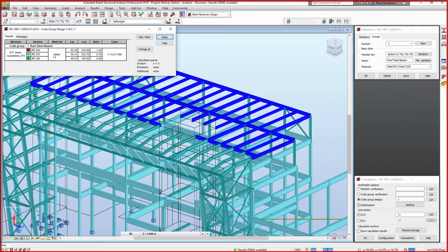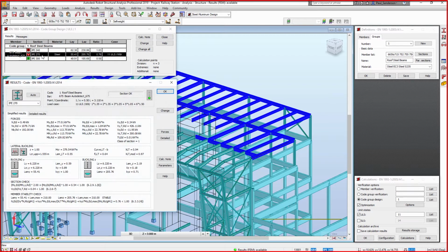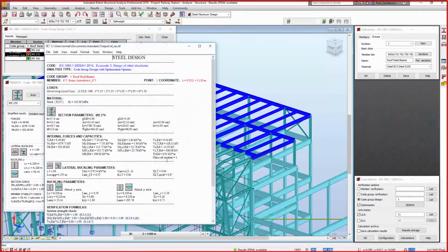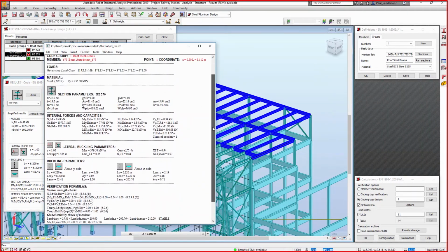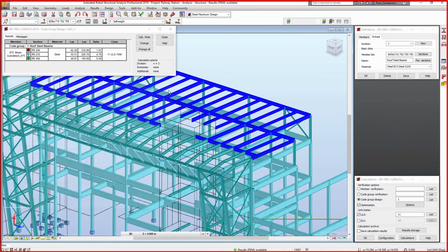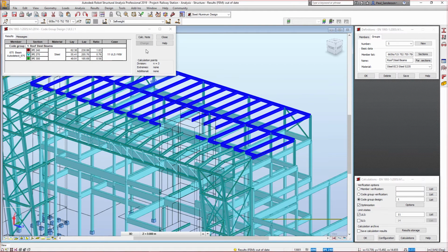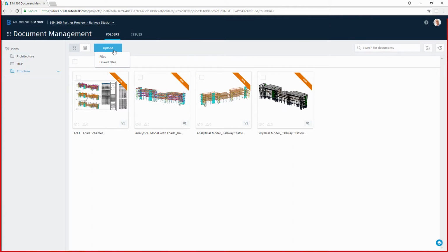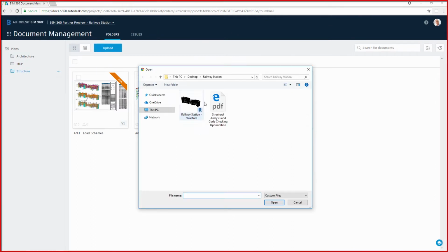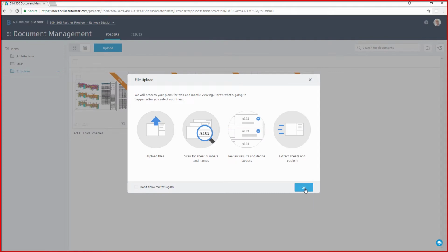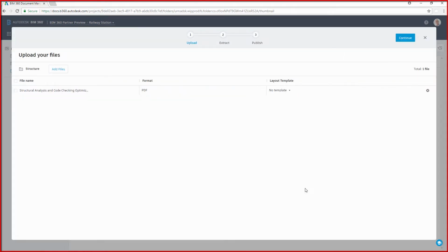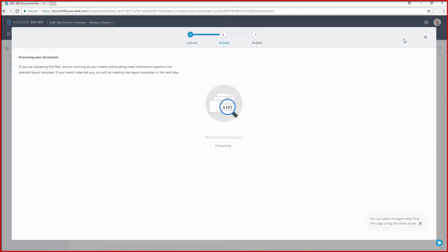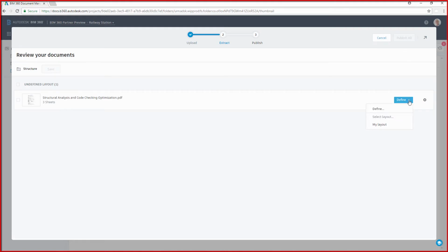The engineer can also select optimization criteria. Once the design group is optimized, a simple Change All button allows all new sections to be applied to the model. When design changes and analysis have been completed by the engineer, the information can be brought back into BIM 360 Docs to allow the designer to review the design changes and update the physical model accordingly.